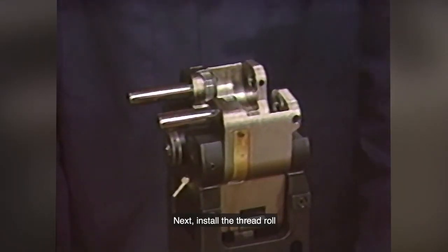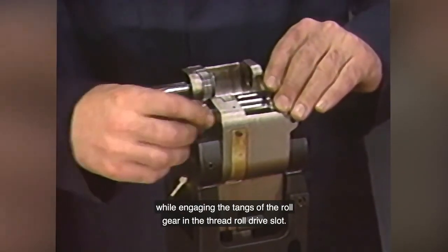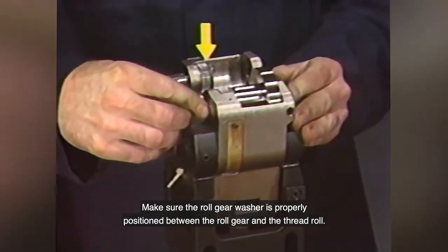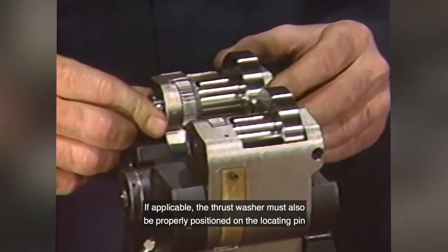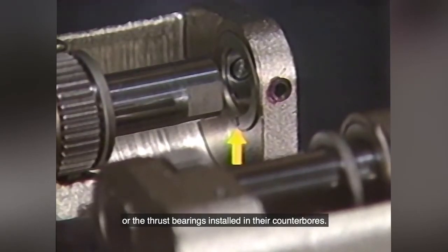Next, install the thread roll while engaging the tangs of the roll gear in the thread roll drive slot. Make sure the roll gear washer is properly positioned between the roll gear and the thread roll. If applicable, the thrust washer must also be properly positioned on the locating pin or the thrust bearings installed in their counterbores.